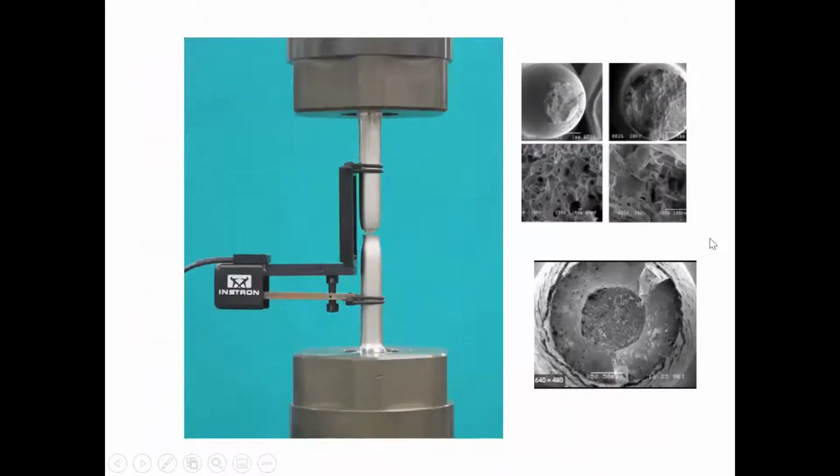So here's an example which has been broken. In a moment, I'll show you my own. So this is the top grip and this is the bottom grip. And this thing here is called the clip gauge, which is measuring the distance between them. So it's measuring what we call the elongation. The idea is that we pull them apart. Let's say, for example, the top grip is moving up and the bottom grip is moving down. We're stretching the sample. So the distance between this point here and this point here is increasing all the time as we pull the sample apart.